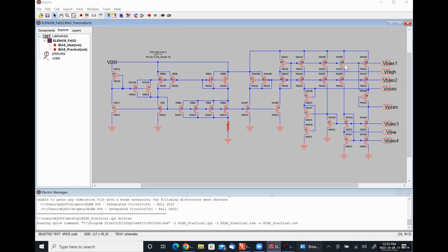And then we have these transistors over here. This one and this one together in a cascode are the reference current for the NMOS based wide swing current mirror that's located down here. So we're going to look at what I have labeled as MN ref1, ref2, and then MP ref1 and MP ref2, and see how things are doing.